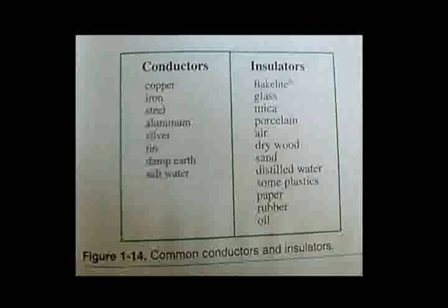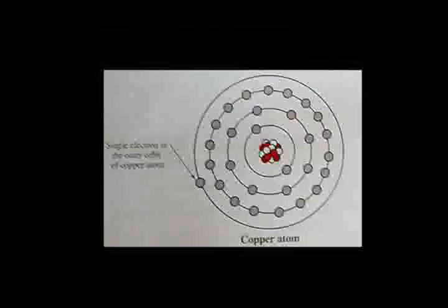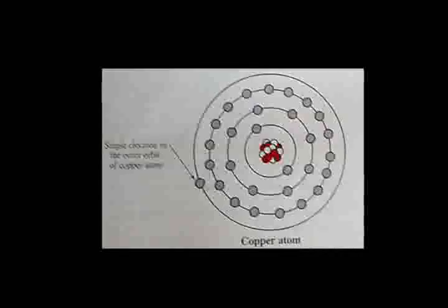The Earth's conductivity is primarily dependent upon its organic composition and on the minerals found in the soil at any given place. The amount of moisture in the soil also determines the amount of resistance in the soil. Moisture can affect the electrical conducting ability of many materials. It can even cause an insulator to become a good conductor. Take wood as an example to illustrate this point. When wood is dry, it is classified as an insulator, but when wood becomes wet or moist, it behaves more like a semiconductor.